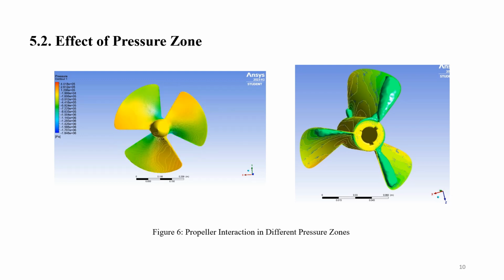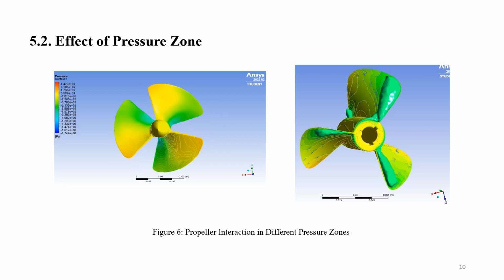For the non-multiphase model, on the left side, figure 8 depicts different pressure contours at all possible regions in the propeller blade. There is a sudden pressure drop at the leading edge and at the tip of the propeller blade, as observed from the static pressure contour.